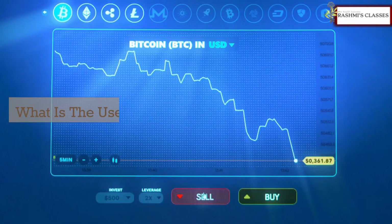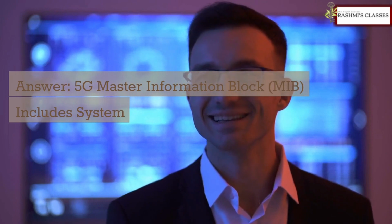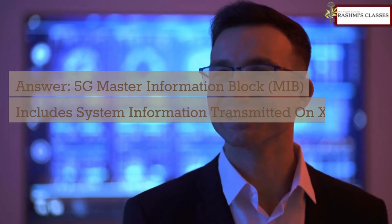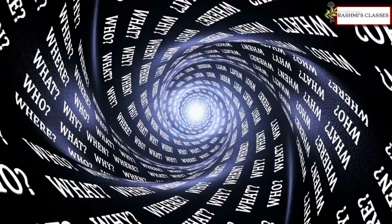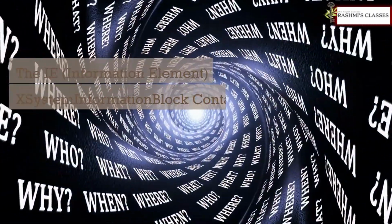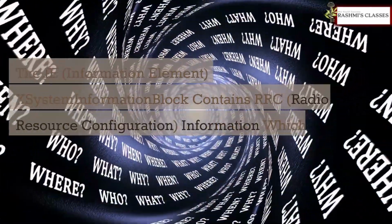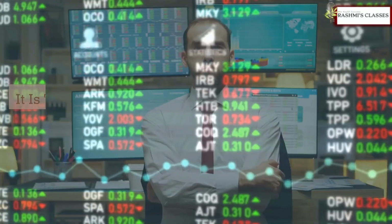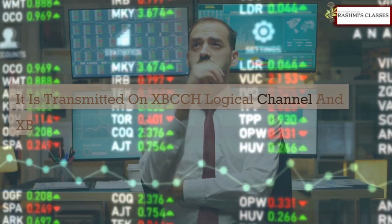Question 16. What is the use of MIB and SIB in 5G? Answer. 5G Master Information Block, MIB, includes system information transmitted on BCH transport channel and BCCH logical channel. The IE, information element, system information block contains RRC, radio resource configuration, information which is common for all UEs. It is transmitted on BCCH logical channel and BCH transport channel.